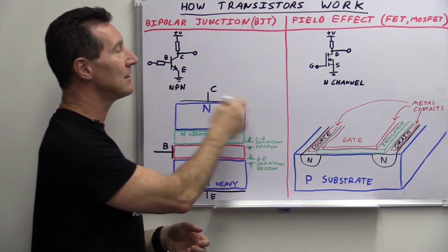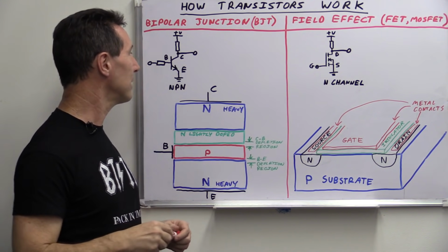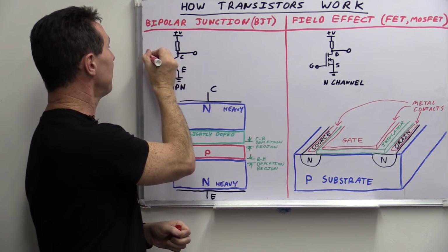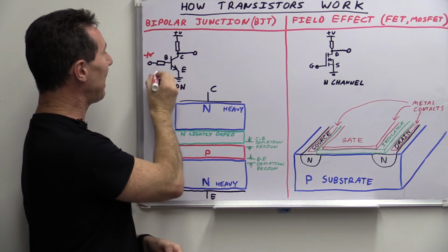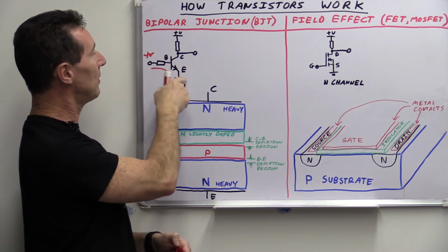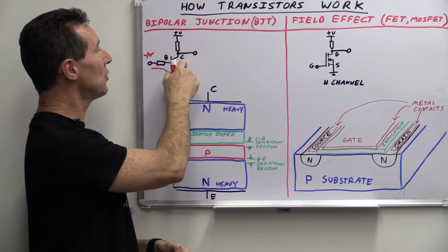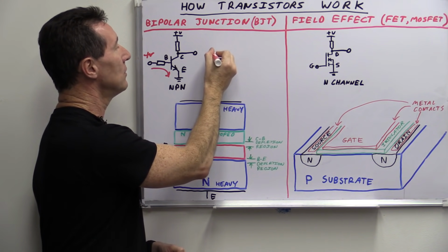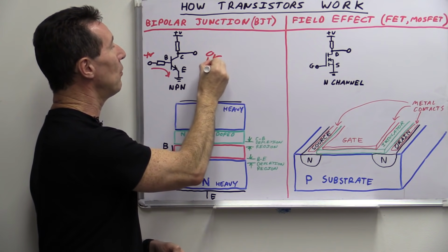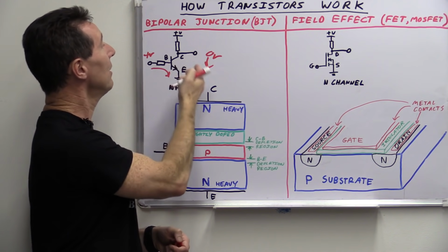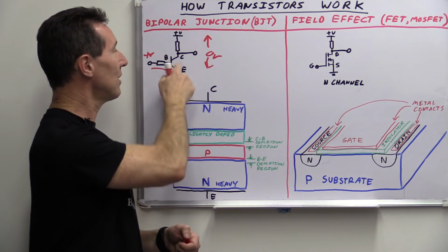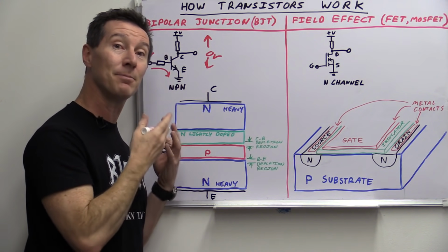We're going to look at the NPN type and the N-channel type only here today, and you should be familiar with these at the circuit level. If you put a positive voltage on the base, then you're going to get current flowing through your base emitter junction there. It's going to turn your transistor on, and your output voltage here is going to go to 0 volts. It's going to be pulled down, and if you don't have any base current, then it's going to go positive. By nature of the pull-up resistor, the transistor is going to turn off. So it's acting as a basic switch.